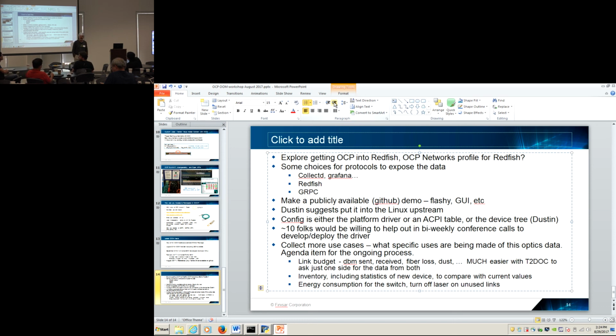Okay. So if you want to turn off the power on those lasers, we could turn it off from the driver, or we could turn it off by accessing the EEPROM. Steve, do those have different power characteristics? If I use the pin for TX disable, or if I use the EEPROM for TX disable, do they do the same thing? Those two for TX disable are the same. But many of the modules have what's called a low power mode. Literally, it turns off the receiver, clock data recovery circuits, and lasers. The only thing it leaves on is the monitoring, the core CPU, so that you can tell it to start up again.